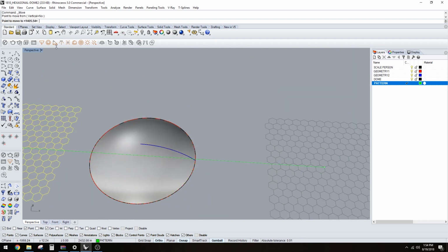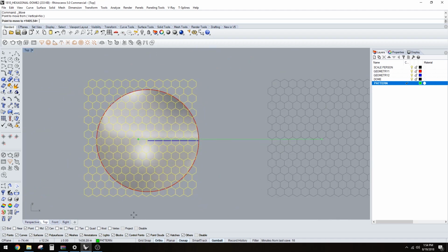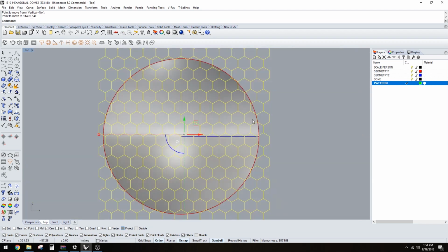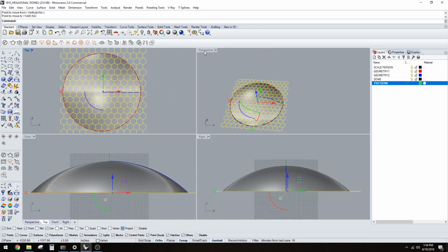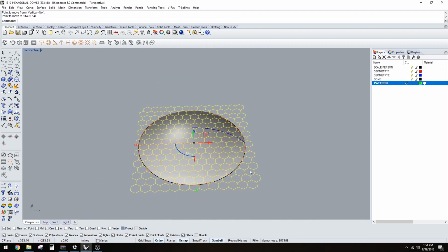We're going to take that from that intersection here, go to the top view, and project it, make sure that it's exactly in the center. And we can see that this line here and that line there are pretty symmetrical, and that's because that'll make sure that everything is developed correctly. So once you have the pattern there, you can go ahead and create the points that we're going to project.